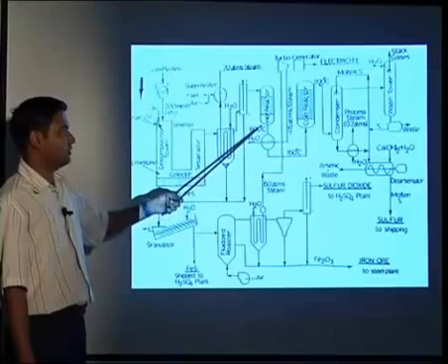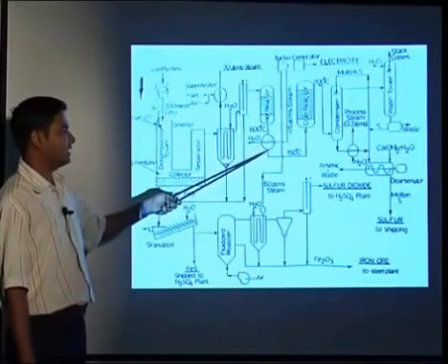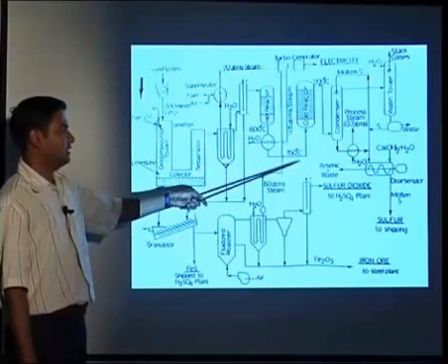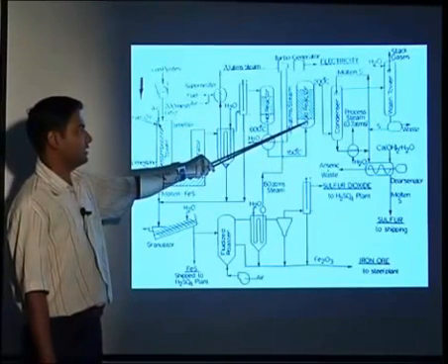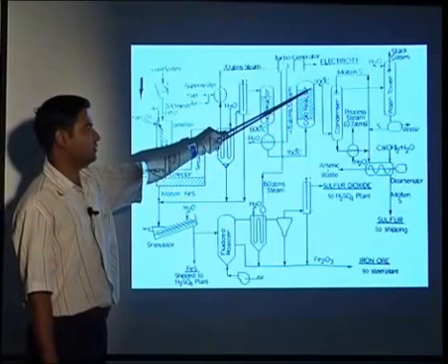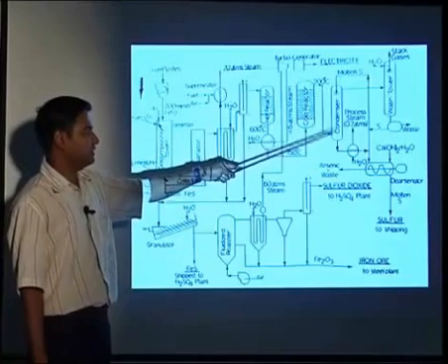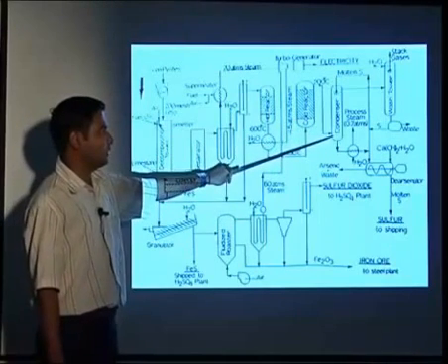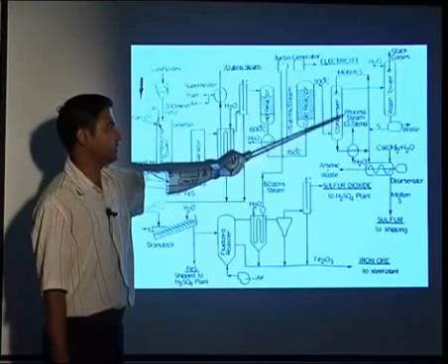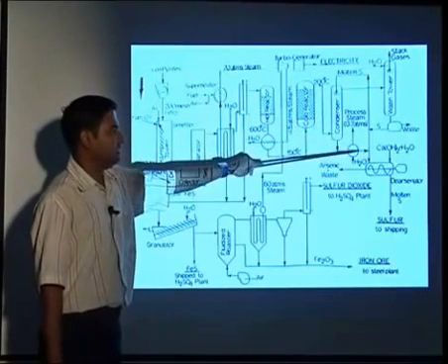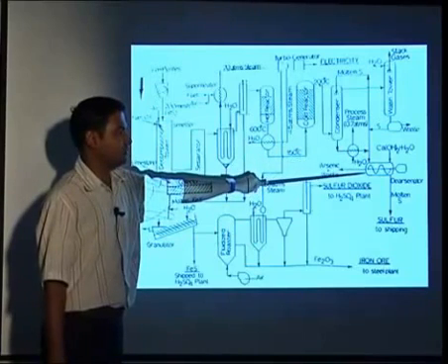So here is the hot reactor, because the temperature is high over here. From here we are getting the heat out, and then we are cooling it down. We are feeding it to the cold reactor, where the temperature will go around 200 degrees Celsius, and then the converted gas will go to the condenser to cool. Then here we get steam of 0.7 atmosphere, that is low pressure steam. And then the molten sulfur we are getting in this storage.